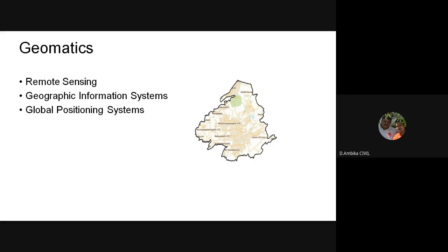So here is the case study where we study the traffic flow analysis and determine the demand for the population of vehicles by PCE and PCU. By analyzing the passenger car equivalent and unit using GIS, that is Geographical Information System, we will predict the amount of vehicles in demand and the need for bridge construction. Again, we are going to suggest this to the municipality or corporation of the Salem District.